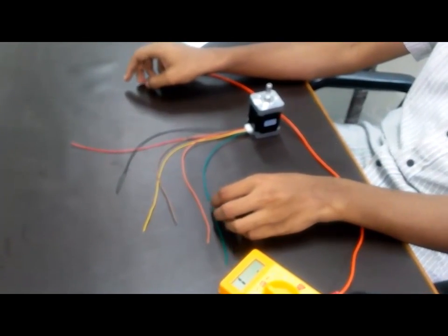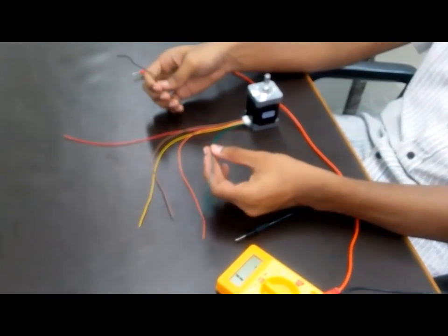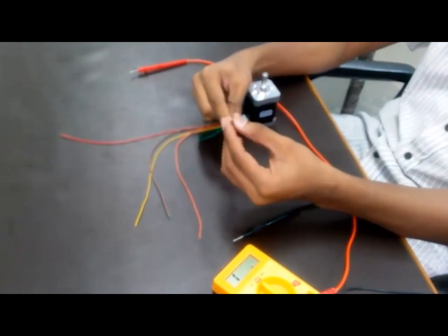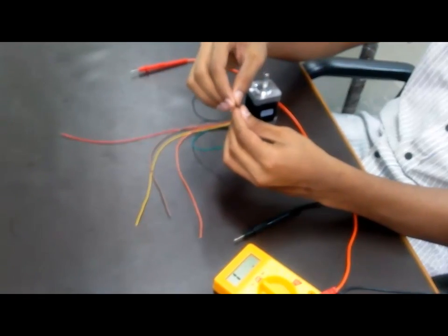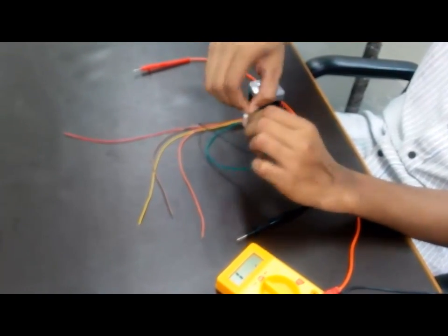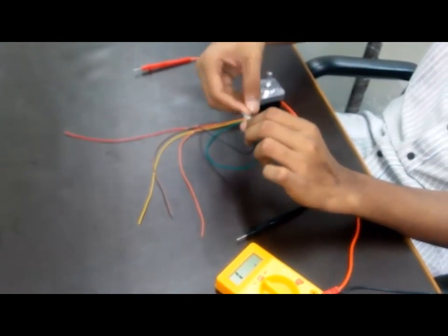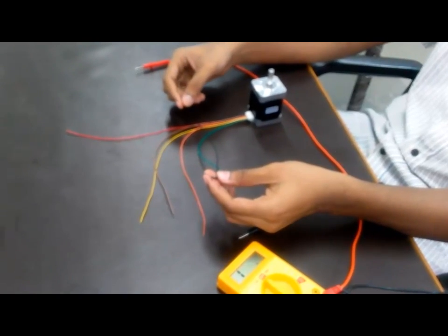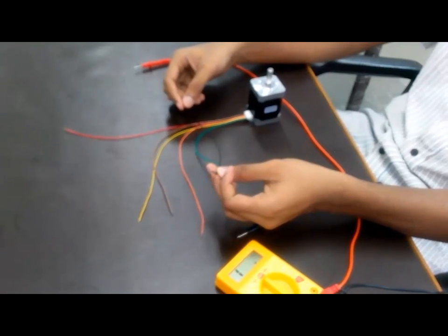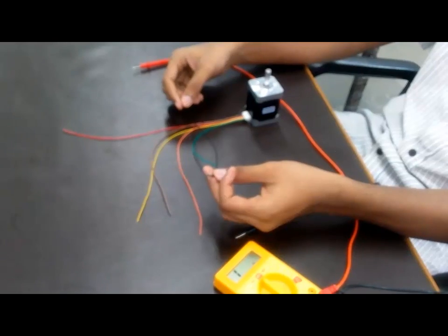By this we have identified that the green and the black wires are common wires. We will short them together and treat them as one. Note that the order of the 4 wires cannot be determined by this method. This can only be found by actually running the stepper motor with random assignments of connections and swapping the last two if it just wobbles instead of rotating.